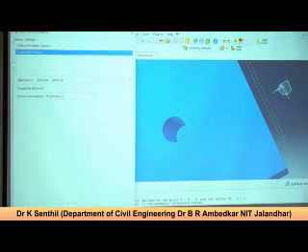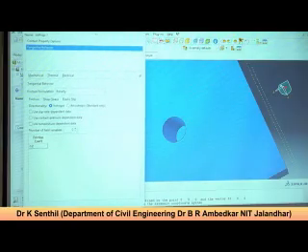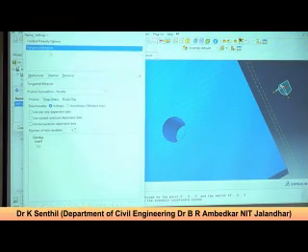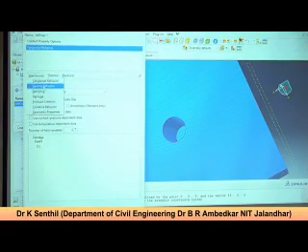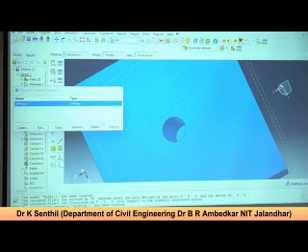Mechanical behavior, tangential behavior. You have to keep, of course there is friction between the soil and other things. So the penalty based contact algorithm that you have to use. The friction coefficient maybe you can keep 0.2, 0.3, but this friction actually impacts your results. So you have to take care, you cannot randomly put something. Another one we have to define is normal behavior, right? The normal behavior is a hard contact, you can keep the default. Now the interaction property is defined.